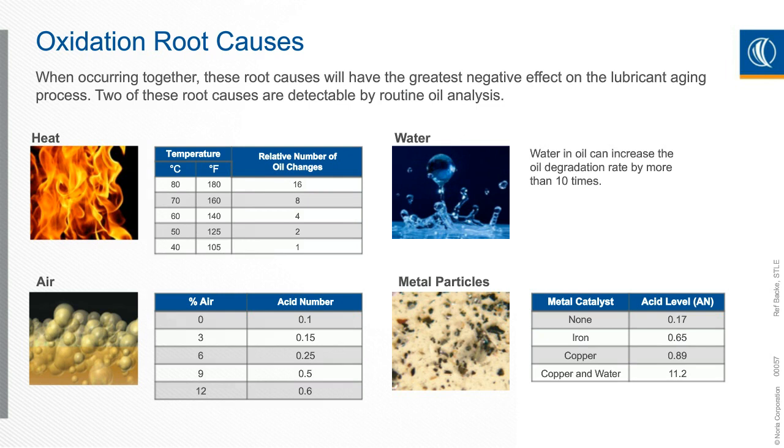Water in oil can increase the oil degradation rate by more than 10 times. It doesn't take much water in the oil to really start having a negative effect. Air as well, not really talking about the air that's sitting in the headspace, but the aeration of the oil, the air that's inside of the oil, especially when water is present as well. And also metal can act as a catalytic substance leading towards a degradative property, such as oxidation in the oil itself.